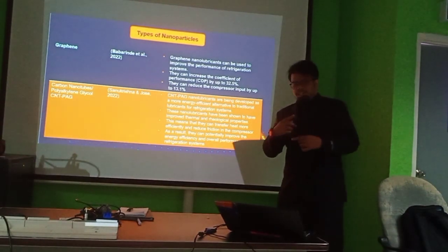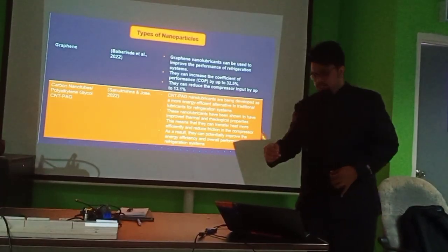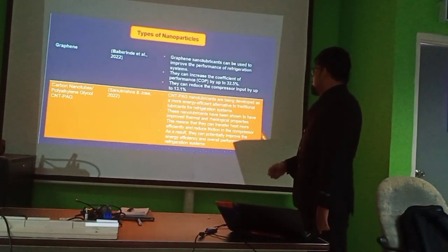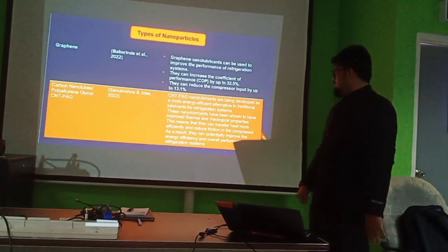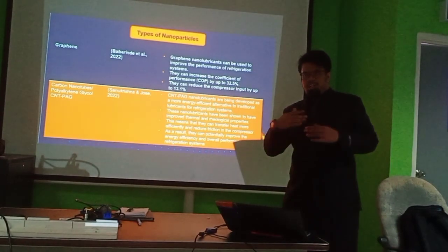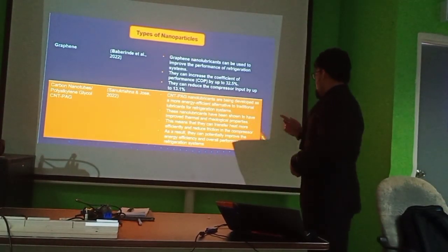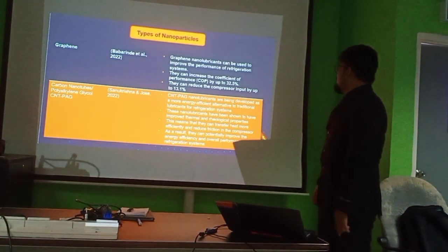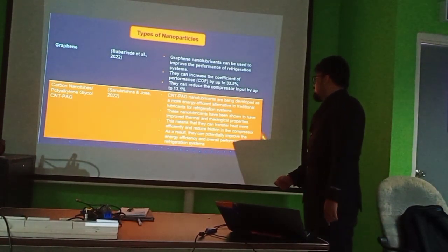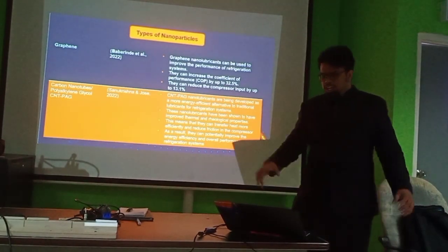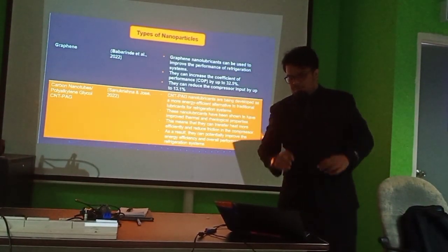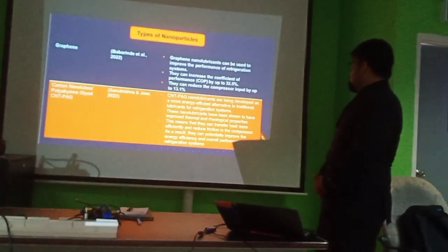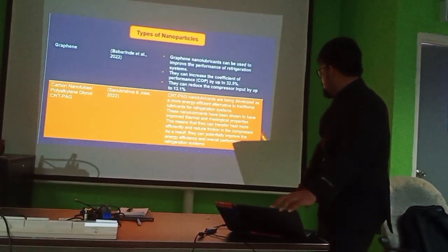And this nanolubricant has been shown to have improved thermal and rheological properties. This means heat transfer is increased and expected to be efficient, and it can reduce friction in the compressor. As a result, they can potentially improve the energy efficiency and overall performance of refrigeration system.